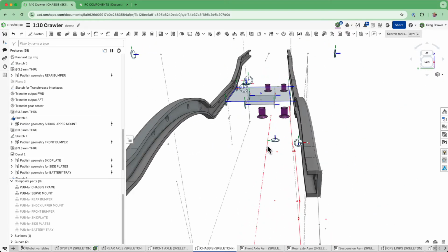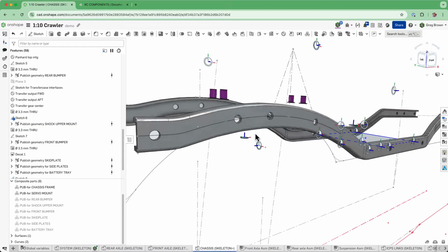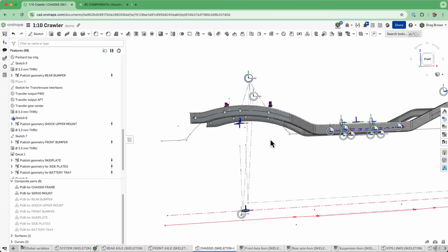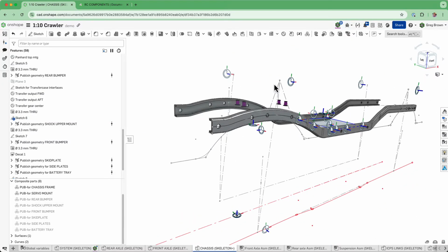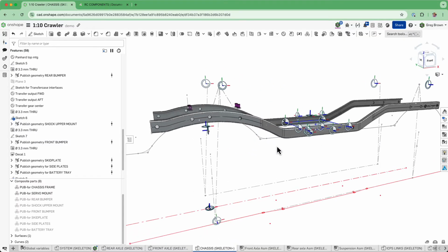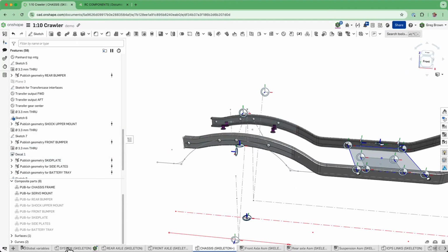So this is the point where we start bringing together some really fundamental datums and a little bit of construction. You can see here I've connected some dots together between the wheel centers, the wheel and the road location, and the length of the shock absorbers, and these are other things that are being driven by those very early structural hard points.